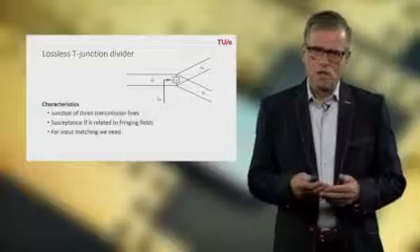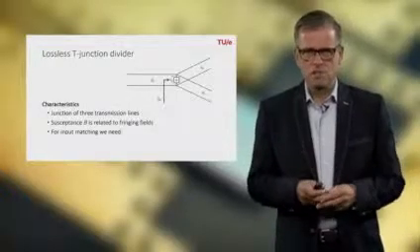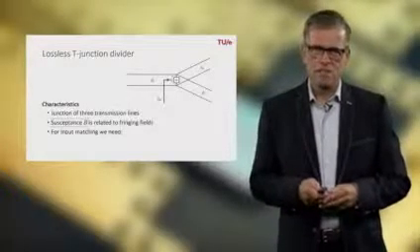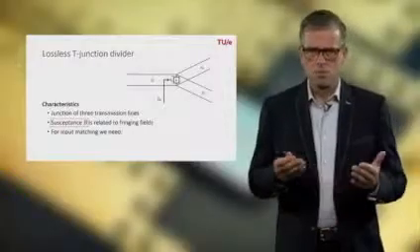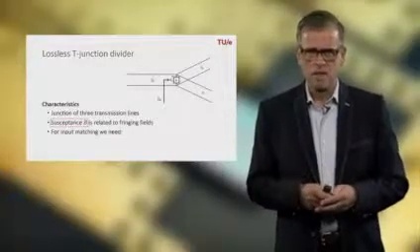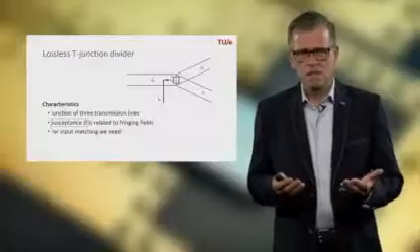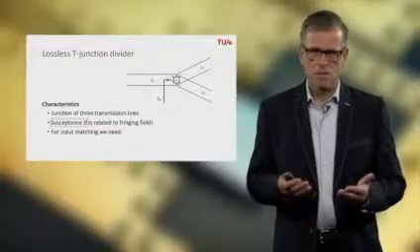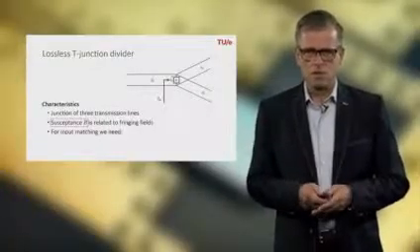In addition, when you connect 3 of these transmission lines at the interface, there will be spurious radiation occurring, and that can be accounted for by adding a susceptance B to this circuit to account for the fringing fields.